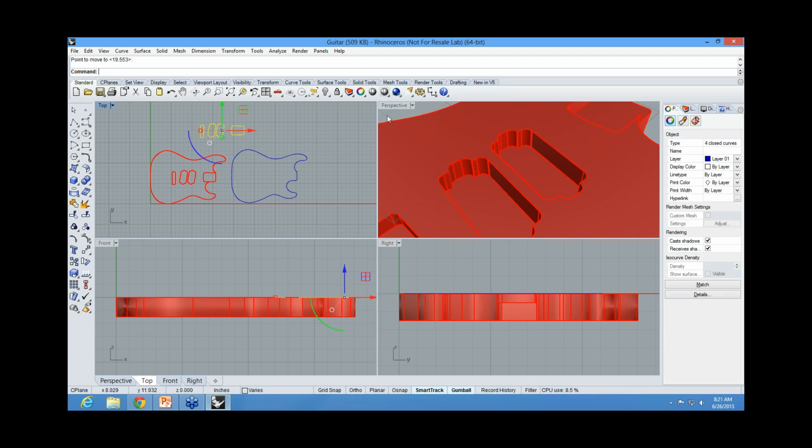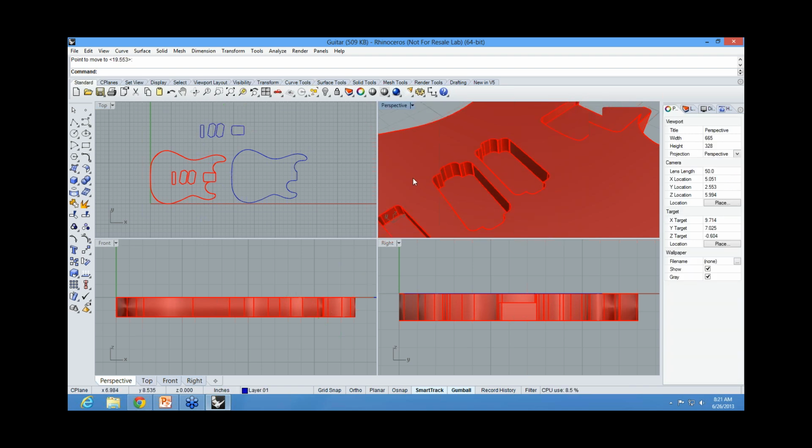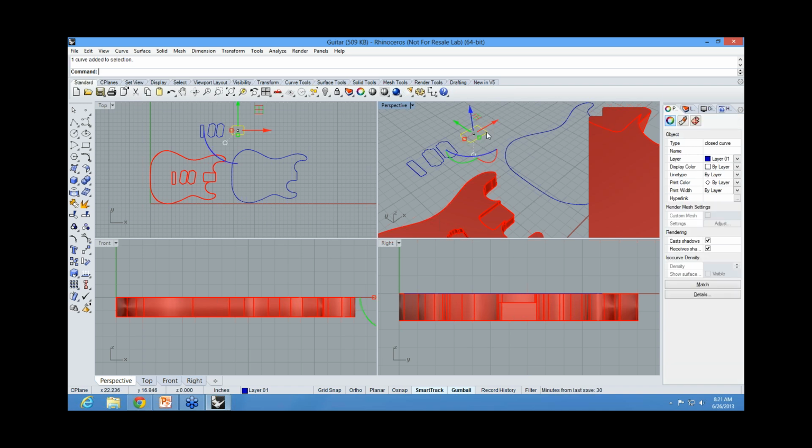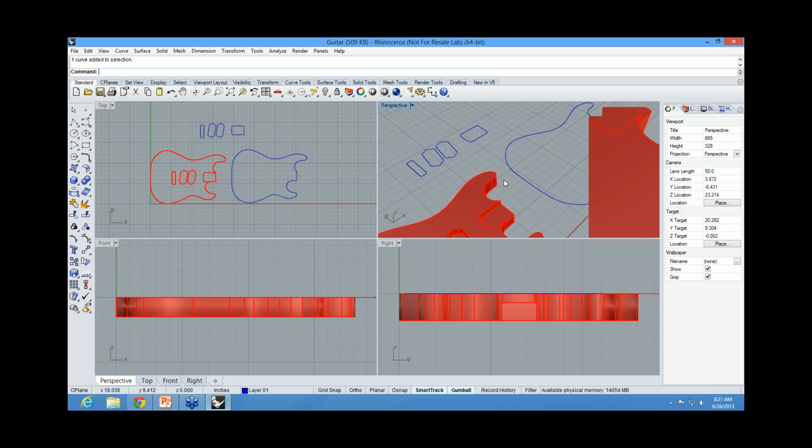And again, these are 2D curves. They're cleaned up. So you can see, for instance, this is a great example. Right up here, this is a nice 2D outline. Could be used for pocketing quite well, although it came from a much more complex set of curves. And so curve Boolean cleaned this up, created a 2D outline, and put it together for me very quickly.